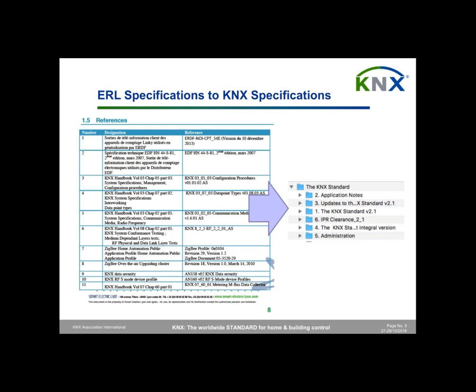The second kind of communication TIC is the standard communication, which is quite more recent and which is based on 9,600 bauds, and which has more detailed fields in the protocol and more information, and which is also able to manage producer or consumer aspects of the meter.